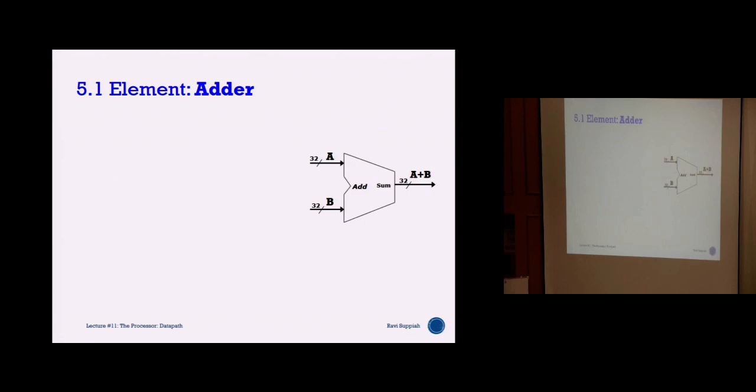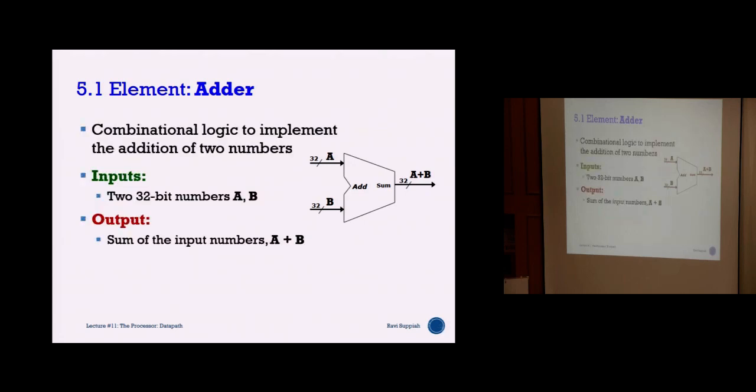This adder is a combinational block. Okay, a combinational logic block does not require a clock. So the moment I say it's combinational logic, that means there is no clock involved. Which means when I provide an input, the hardware will just trigger and generate the output. So in this case, I'm trying to add two numbers together. A plus B, I get the result A plus B here. In our case, this B is fixed at value 4, correct? So it just becomes PC and PC plus 4 as the output.